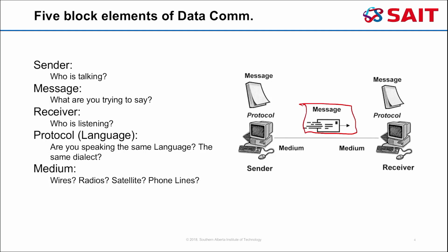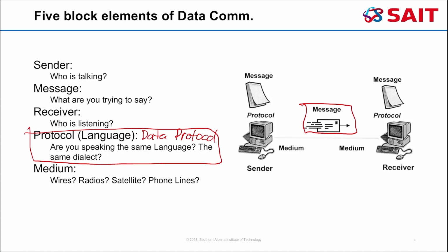Well, within the message, what defines the meaning of those ones and zeros is something called the protocol, or the language. And I tend to take it a step further and just call this the data protocol. Because what we need to understand is there's really a difference between a data protocol and a physical protocol. We've been talking about RS-232. RS-232 is a physical protocol.